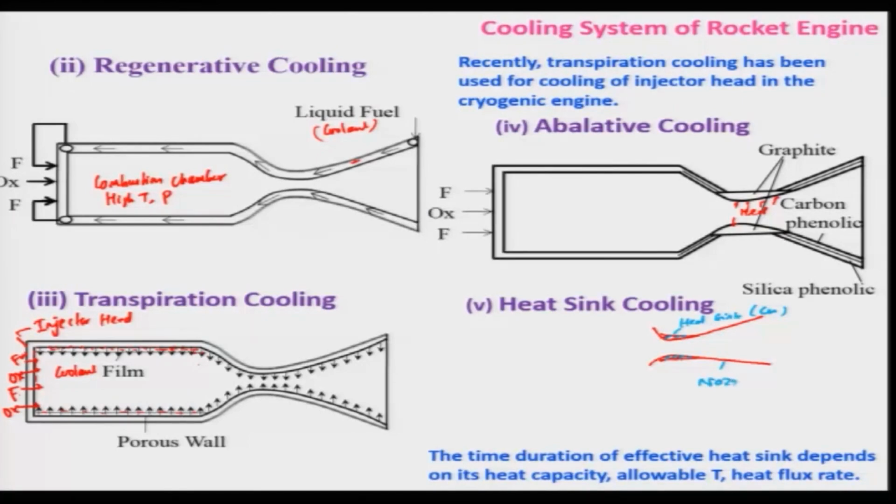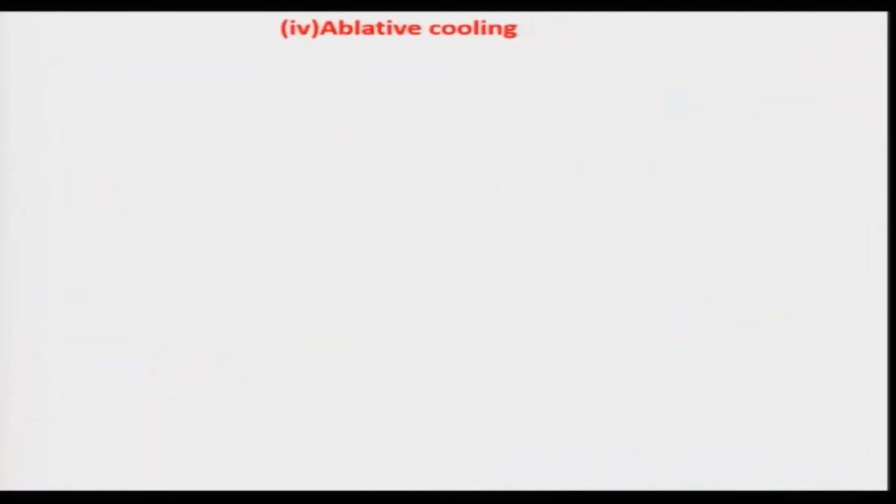So, therefore, this is being used for a short duration, and particularly for the solid propellant rocket engine, where you do not have liquid fuel to be used as a coolant. And so the ablative cooling is also used for the solid propellant rocket engines, and we will be discussing a little bit more about the ablative cooling.